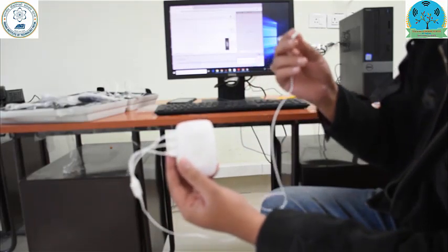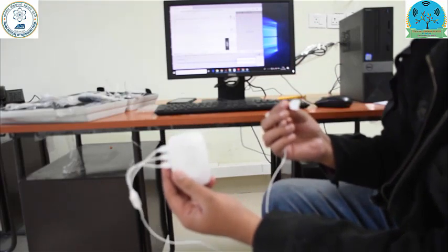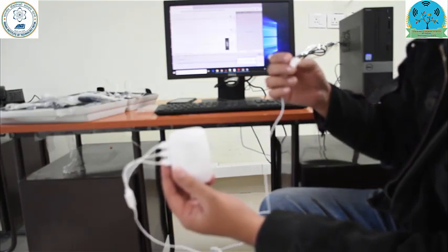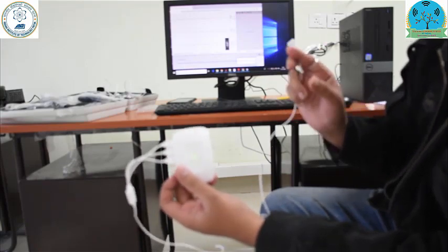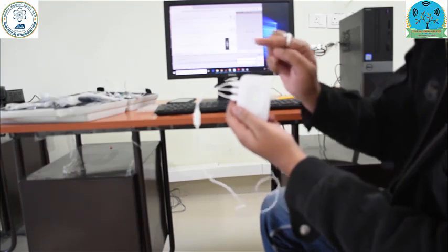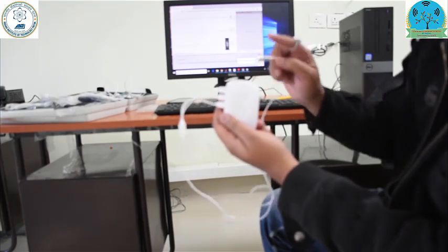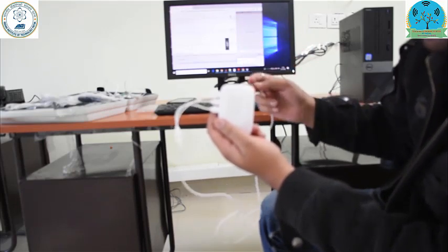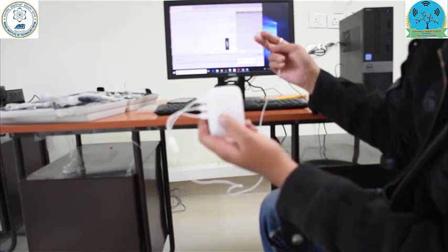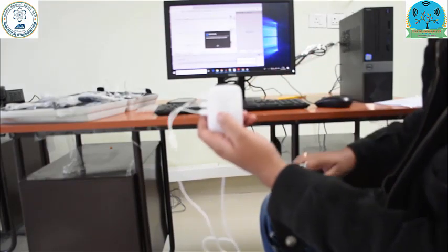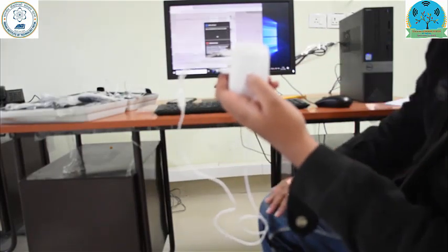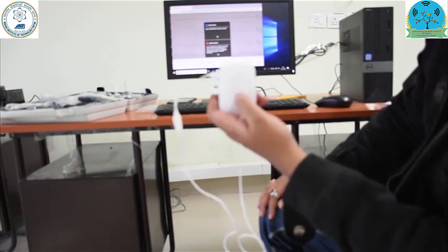So this is how we can use the accelerometer on human body for an activity recognition, which is also a very important task for any biomedical signal analysis. The most important lesson here is we should understand that the right number of channels deployed on the microcontroller, those many channels also should be enabled on the OpenSignal software. Then only the communication will happen between this microcontroller and the device. So as you can see, when I turned off the microcontroller, the message came, device turned off. So as long as you want to measure the device, you can turn it on and record all the sensors.